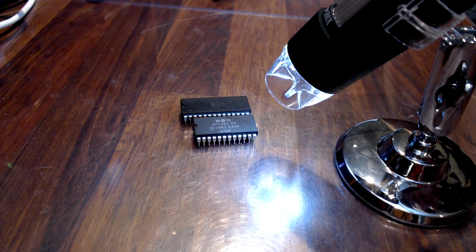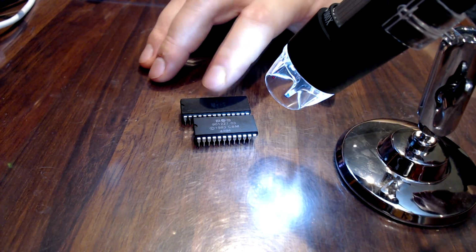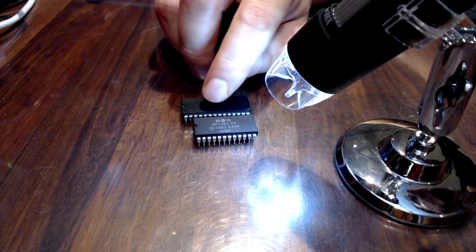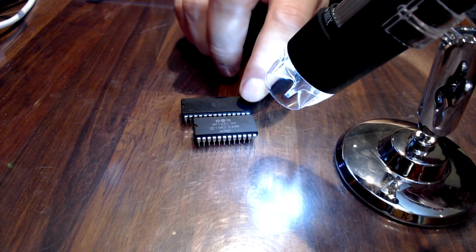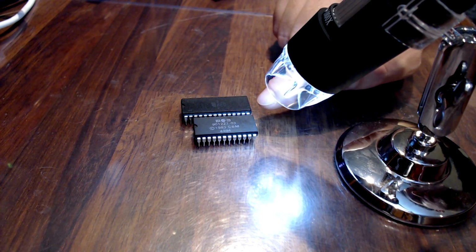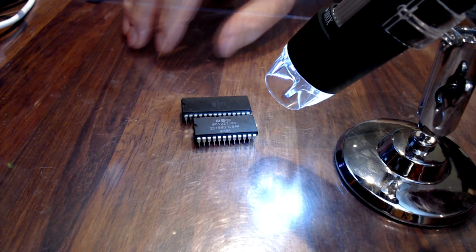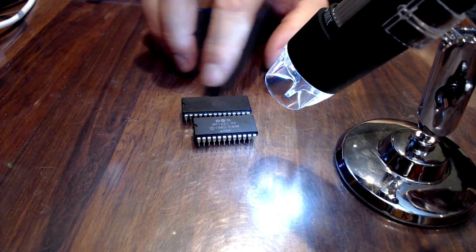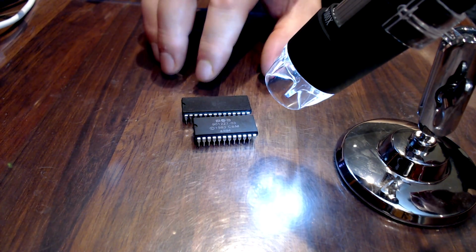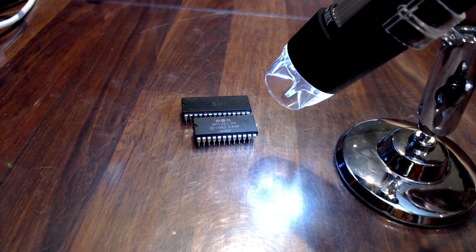So the EEPROM has 4 more pins. It has more address pins because it's a bigger chip. The pins on the left side of the EEPROM are the same as on the original kernel. So both of the left side pins are the same. But on the other side there are some pins that are in a different order. So we need to make a converter for that.